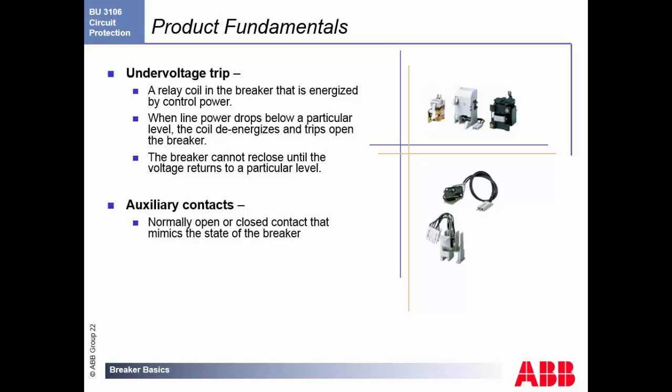If you have a 480-volt motor and you're starting to see 400 volts on that motor, you're going to really stress the windings of that. So what this allows you to do is set a level as to monitoring the voltage coming into our breaker. And when it dips below that, this shunt will recognize it and open the breaker automatically.